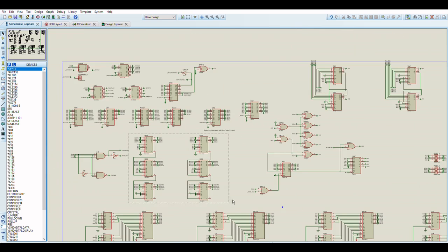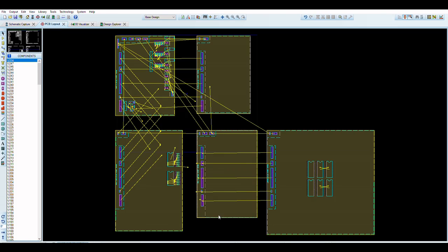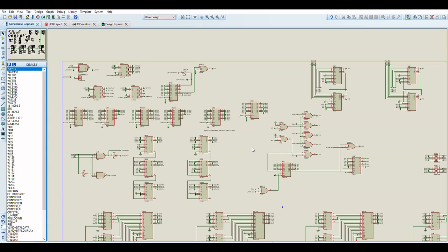Adding all of these extra adders did make things... Adding these extra latches for the internal scroll registers and adding the extra adders did add quite significantly to the size of the board, but it's still medium size compared to the character board. It's still in the middle of the Sprite board, so it wasn't too excessive.